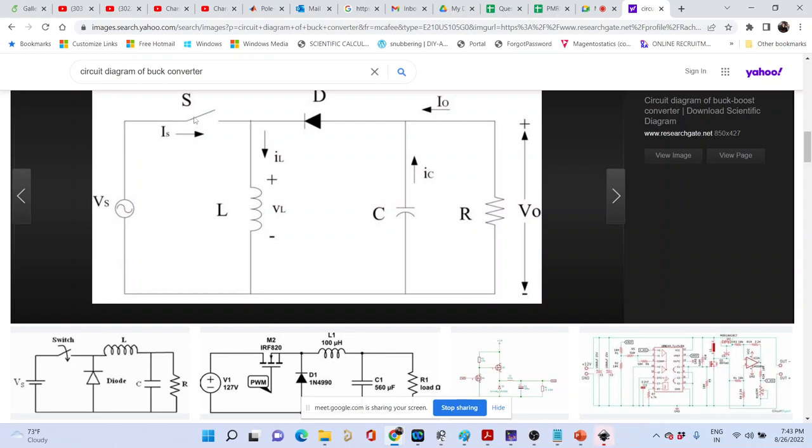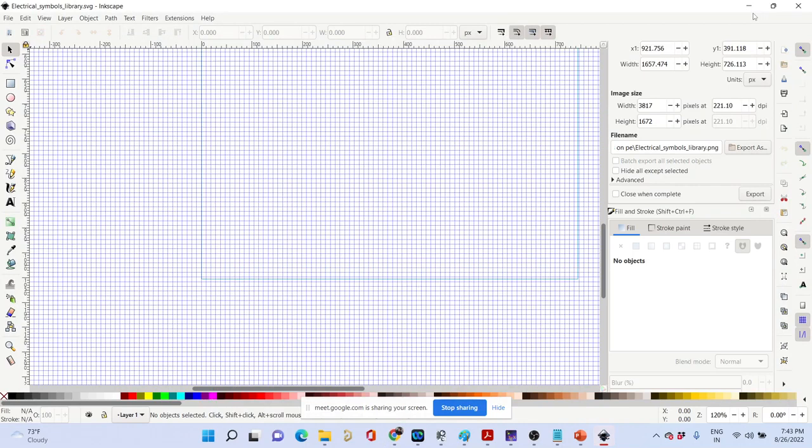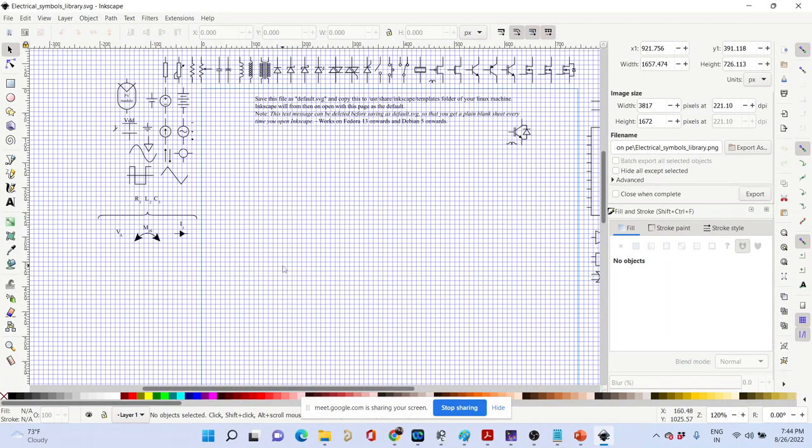So if I place a switch over here, then the drain terminal will be over here, the source terminal will be over here, and the gate terminal will be over here. So now these are zero potential, and you are applying 10 volt at this potential. The confusion that we had in the previous case, whether we are actually applying 10 volt or not, is now clear. This point is fixed at zero potential now, so I am applying absolutely 10 volt at the gate. Are you getting my point?